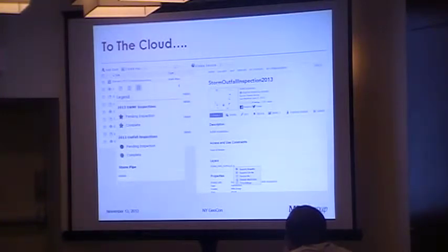All right, 9 minutes. Back to the most important thing that I almost skipped. So you see here, this is set up in our ArcGIS.com map. They were inspecting the ponds and the outfalls. When I set up the attribute table, I put in a field called inspection complete and made it yes or no. By default, I set every inspection to no. So just by simply symbolizing the layers in the map, pending inspection, where everything equals no, and inspection complete,